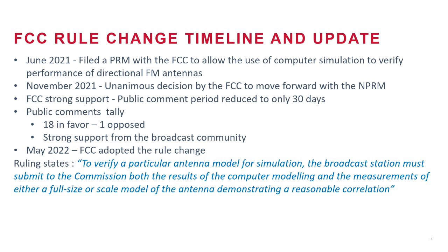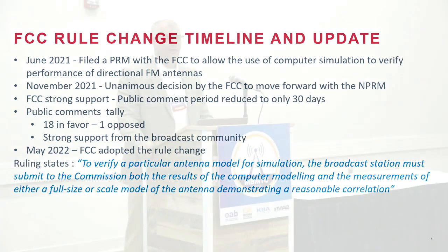And the actual text from the ruling says that to verify a particular antenna model for simulation, the broadcast station must submit to the commission both the results of the computer modeling and the measurements of either a full-size or scale model of the antenna demonstrating a reasonable correlation. So it said, look, if you want to offer this antenna model, for the first one, you've got to show us that the range results and the computer results demonstrate reasonable correlation, right?